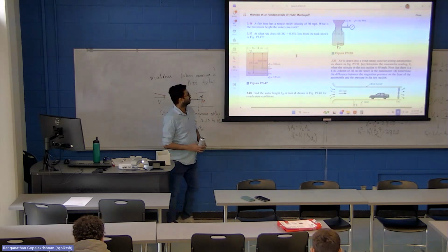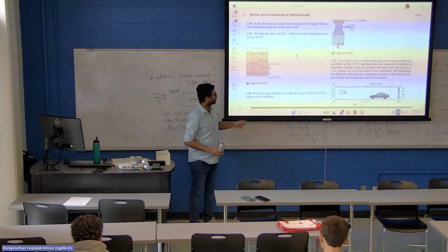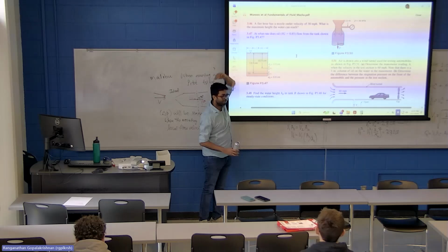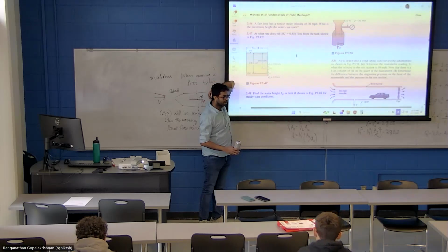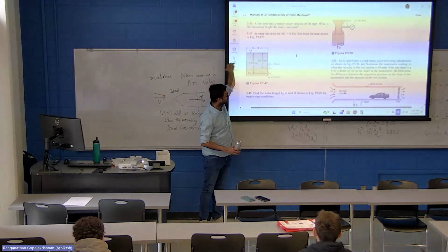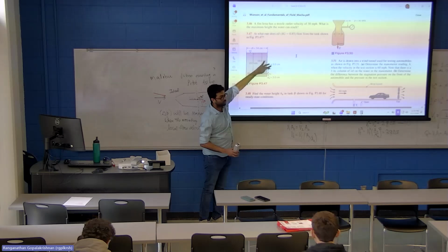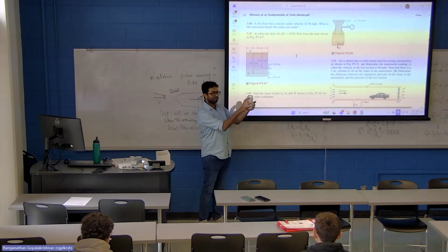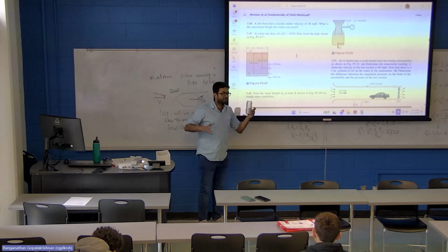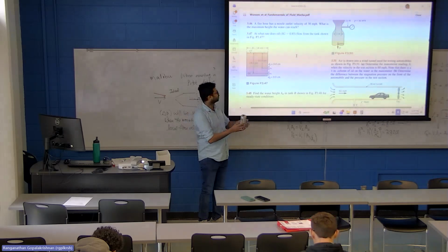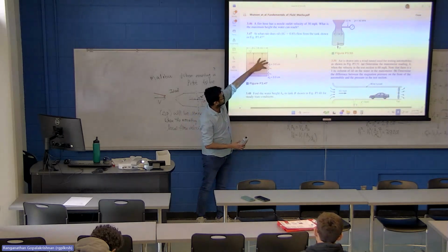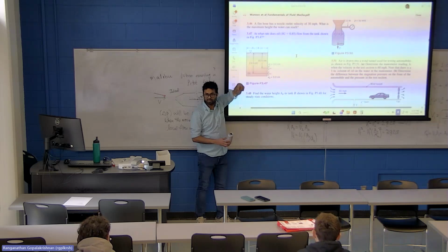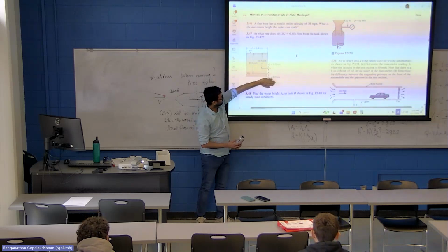Atmospheric pressure. Is it only atmospheric pressure? What about the weight of the liquid that's above this hole, above the level of the hole? That would as well. That would cause the flow to come out, right? The whole point of punching a hole at the bottom is to have the weight of the liquid above push it through, right? So the more the depth, the higher the flow rate is going to be. Number one.